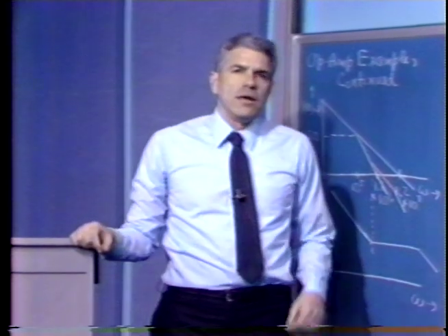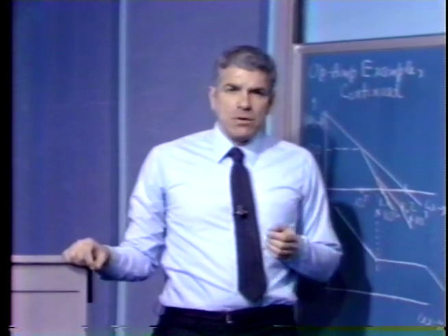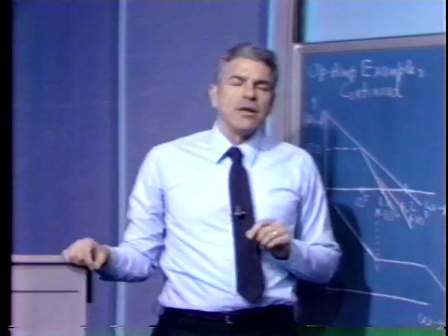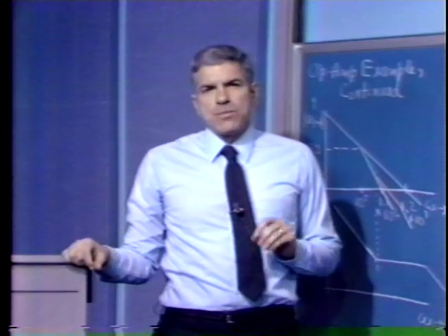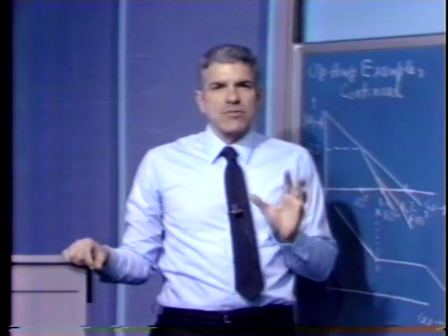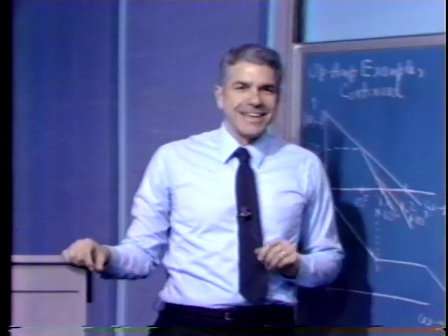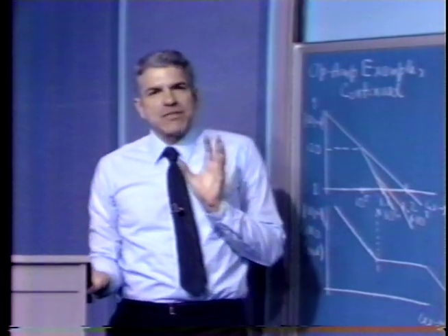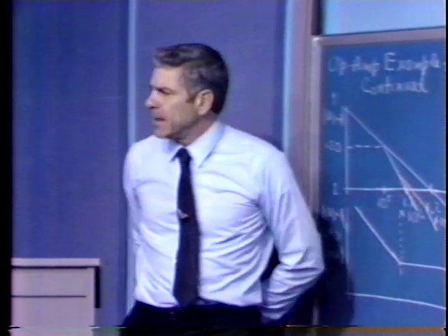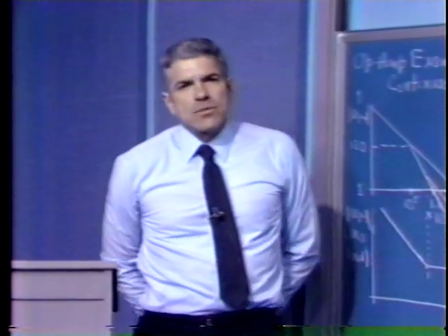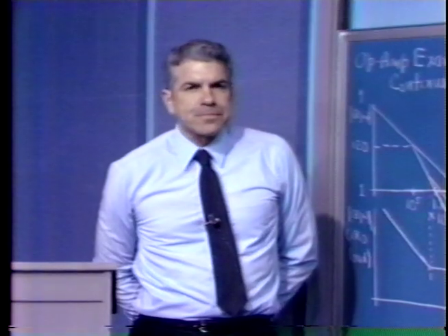Suppose we anticipate an additional pole in our loop transmission, but we don't know the frequency at which that pole will be located. So what we're looking for here is really compensation for those who don't know what they're doing, possibly. Or something where we have a system that has some uncertain parameters. How might we compensate in that case?